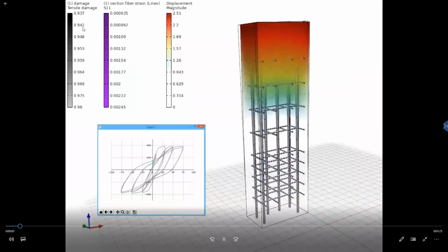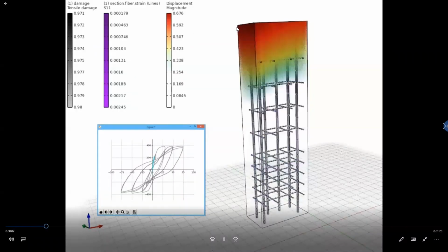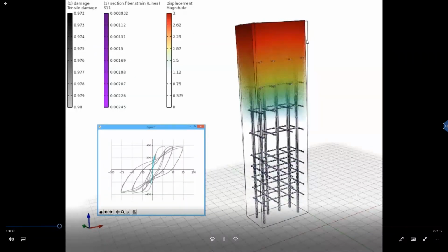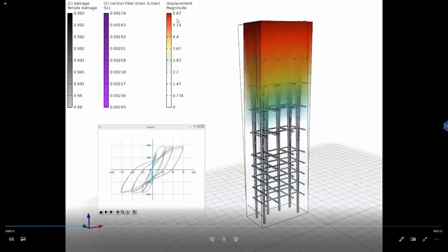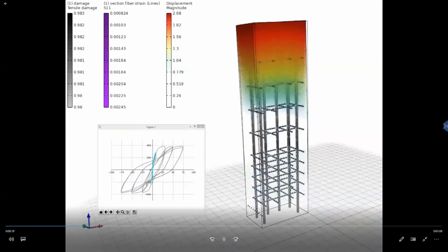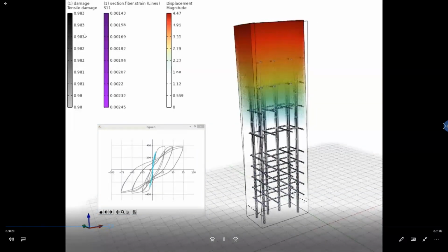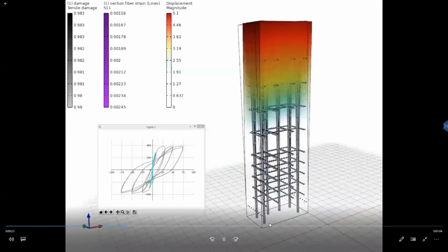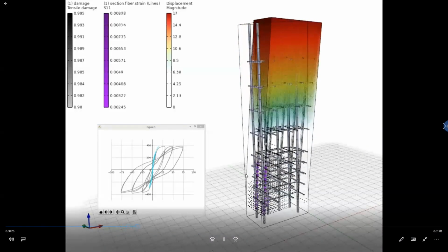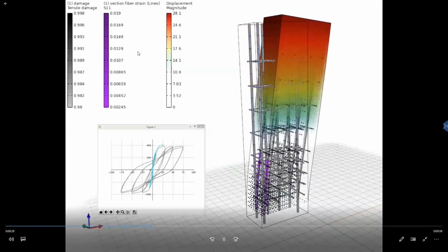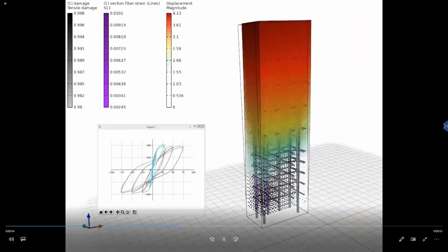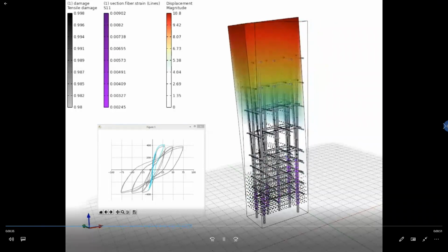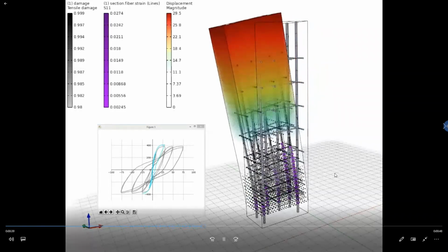Here, for example, we are superimposing the displacement. We are superimposing first an undeformed shape here, so you can see actually the deformation versus the undeformed shape. Then we are using a plot for the displacement using a volume plot, as I showed you before. Gauss plot for tensile damage, which is this one, these black dots here, and then a Gauss plot for the rebars, showing only the deformation up to a certain level, so you can see where this deformation of the plastic hinges, the plastic deformation in the beams. So it can be pretty nice.